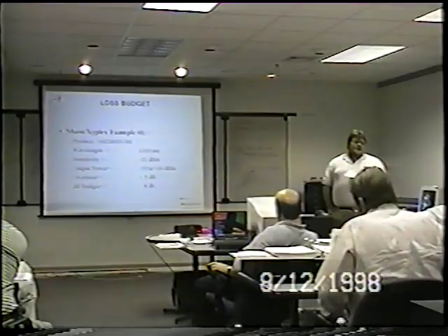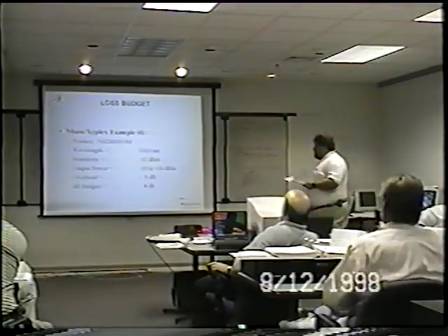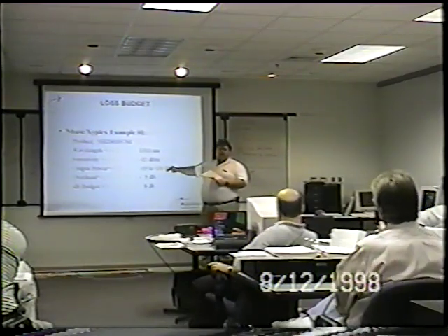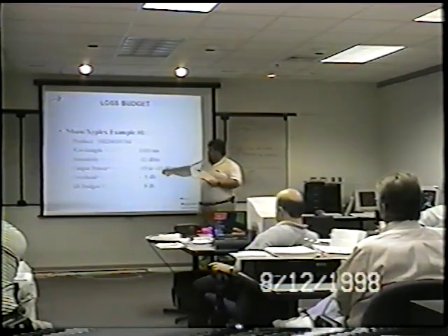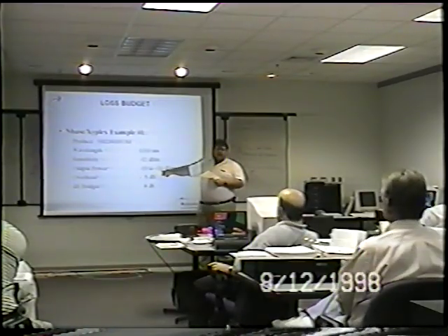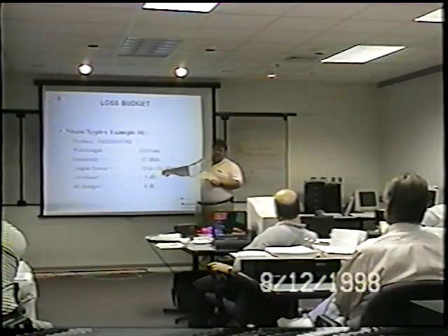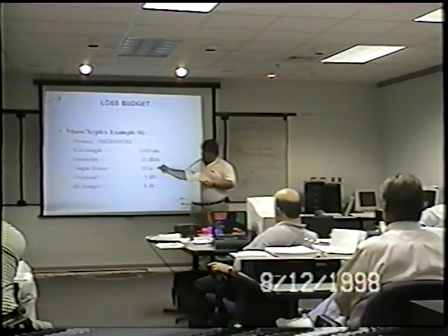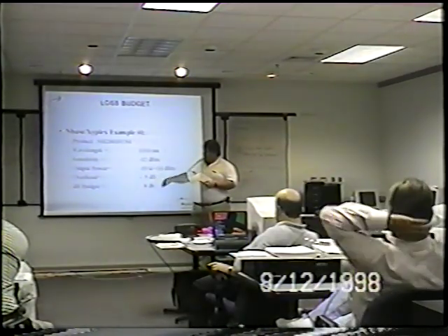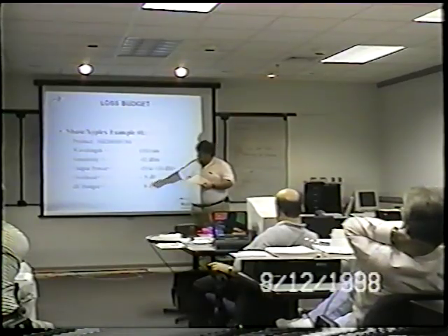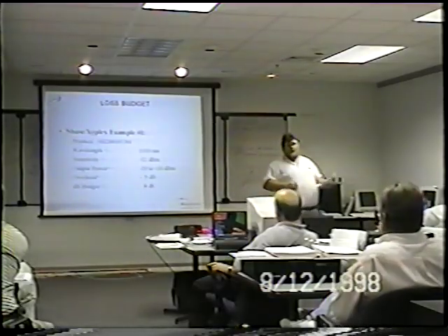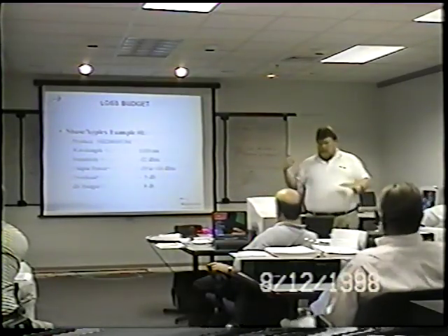Also considered was aging. This will tend to degrade slightly over time. The output power, due to aging, that power output curve, you might start out at minus 14 on the initial install. 2 years down the road, this might be down to minus 16 due to an aging process in the laser itself. So that range allows for that aging. This 5 dB gives you the extra overhead. By taking all of this into consideration, you net an 8 dB usable budget just on the fiber itself. Because in the 5 dB, you've already considered the connectors and everything as part of that.